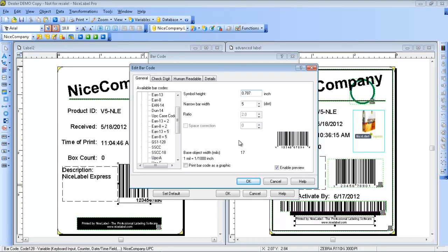But if you have it as a Zebra native barcode font, then it's going to be using Zebra's native language that they created, ZPL. And it's going to send less data down, less characters. Because if you captured the print job or printed to a file, you can see all the data that's being sent to the printer, and you narrow down or limit the amount of commands sent down, so it's going to be a faster process of printing.